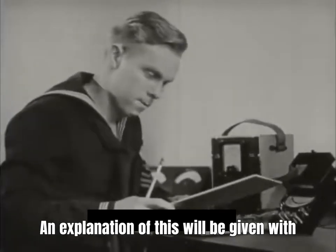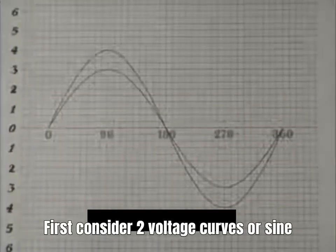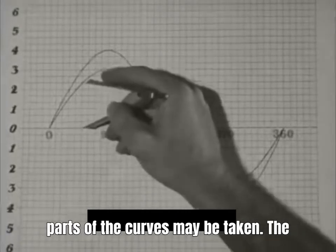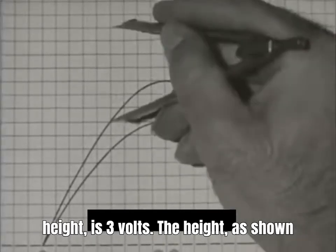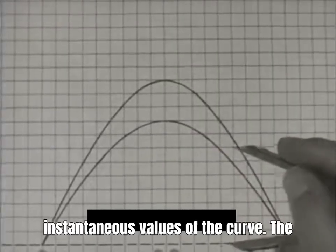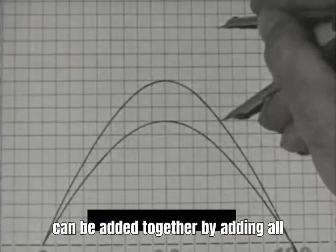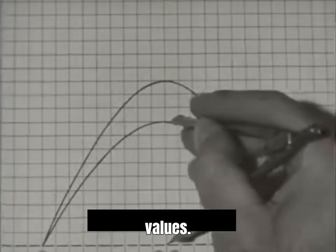An explanation of this will be given with the help of a drawing. First, consider two voltage curves, or sine waves, which are in phase. To add these sine waves, two corresponding parts of the curves may be taken. The voltage of this curve, as measured by the height, is 3 volts. The height, as shown by the dividers, indicates the instantaneous values of the curve. The second curve represents a value of 4 volts. The two curves can be added together by adding all their instantaneous values, and then plotting graphically the resulting values.